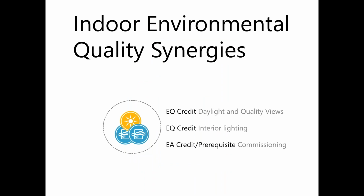Okay, so wrapping up indoor environmental quality, we talked about the daylighting and quality views credit, looking at how much natural light is being brought into a space, and whether building occupants in those regularly occupied spaces have access to quality views. It's not just, do you have a view out a window? Is it a quality view? Can you see interesting things? Can you have that connection to nature? Can you see things that are far away, or see movement of flora or fauna, or things like that?